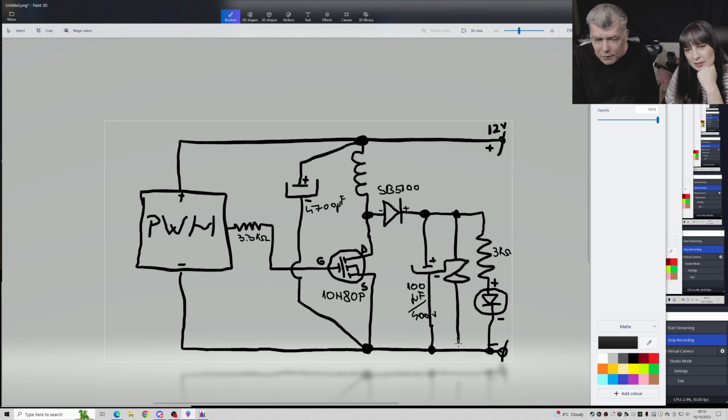That's a Zener diode to here. And on that point, you'll be at fixed voltage until the moment you have too much current. If you have higher voltage here, obviously voltage goes up, current goes up, and at some point you will burn the diode. So the Zener diode in parallel with the output can be used on circuits with low current, but not here.